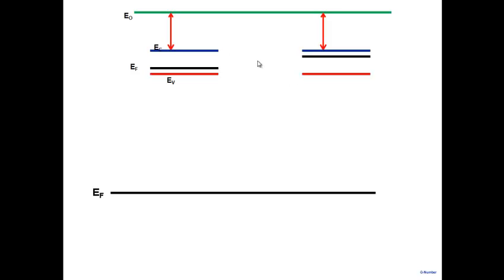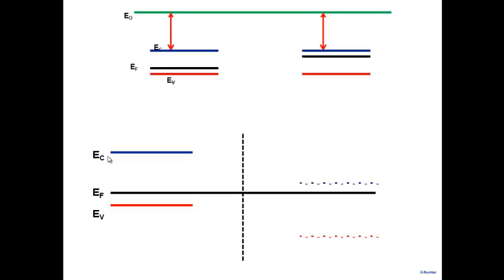All right, so we start off the energy band diagram in equilibrium by drawing EF. EF is constant throughout. We draw the junction, and then we locate these regions far from the junction. We say, well, far from the junction, everything is normal here. So EV, we know, will be away from EF dependent on the doping level here. So we locate where EV is, and then EC, of course, becomes available. Similarly, we locate far from the junction where the conduction band is, depending on the doping.